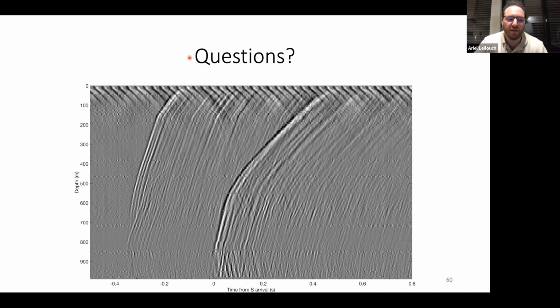Just in my case, I think the difference was that the velocity within the boundaries of the array changes. So you cannot use the same angle for all the channels at the same time. That's why I went through this slightly convoluted application, but basically it's beamforming, at least in terms of the initial assumptions.